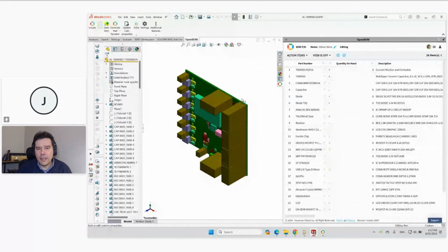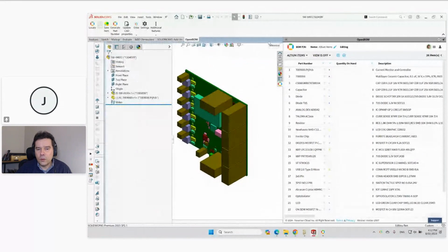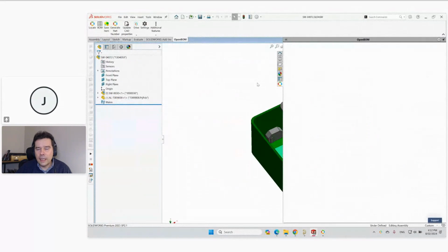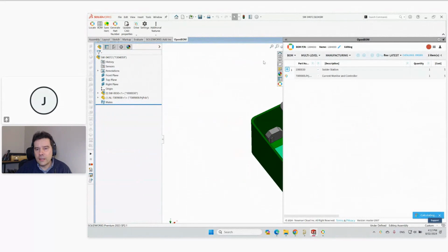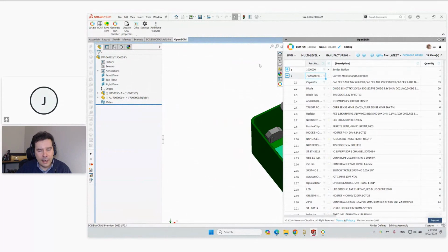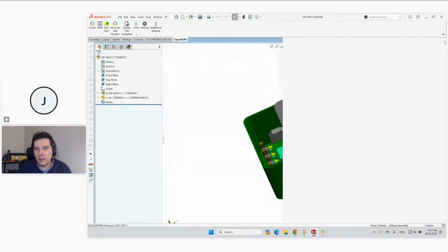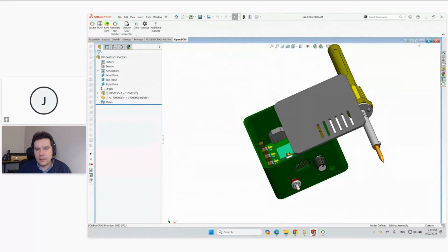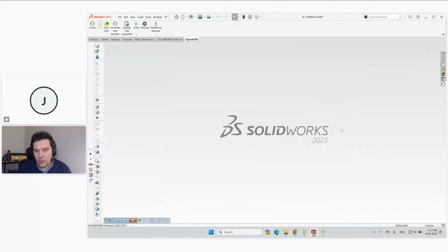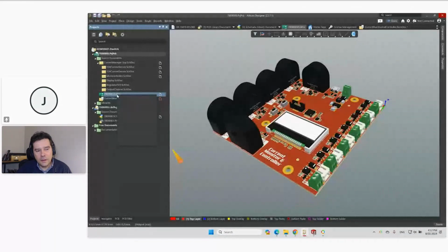So I might take the opportunity to make some recommendations if some of you are trying to do this sort of synchronization between MCAD and ECAD. I'll probably do some examples and some recommendations on how you could do it. So firstly, I recommend to use an IDF file instead of SolidWorks Parasolid.